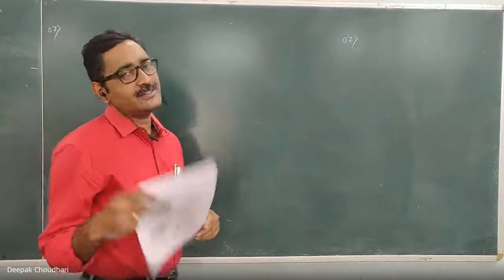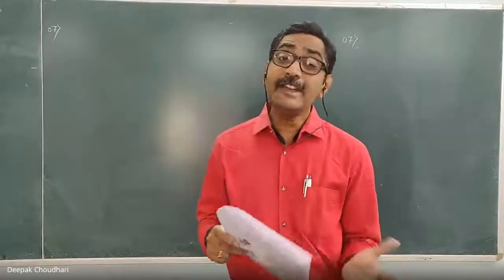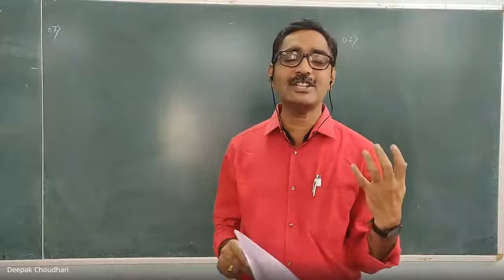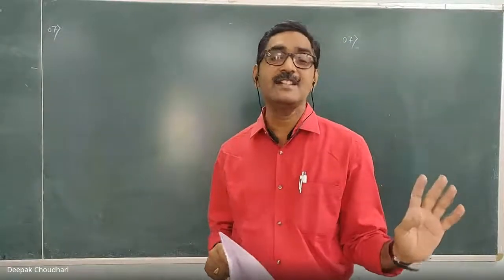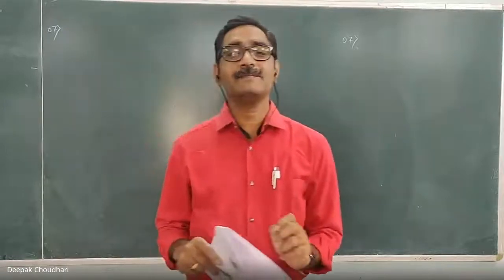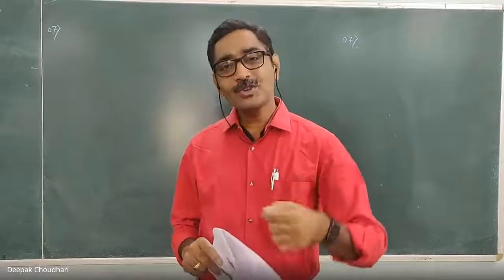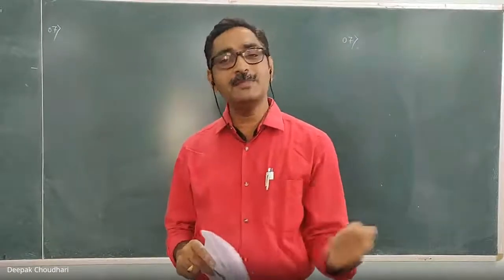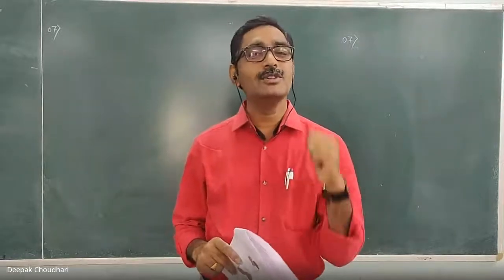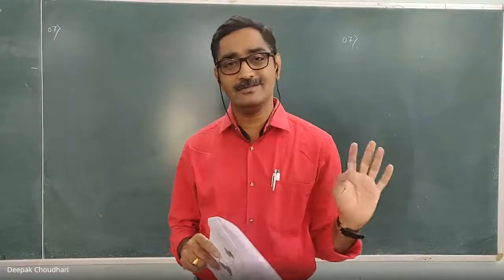Here, look, in equilibrium, even in resultant sums, sometimes the weights are given in Newton. If it is given in Newton, it is a gravitational force and there is no need to make any changes. But sometimes instead of weight, the mass is given in kg. If it is given in kg, you have to convert it into Newton. Multiply that kg by 9.81 so that you will get Newton, and use that Newton value, which is a gravitational force, in further calculation. Don't keep it in kg.